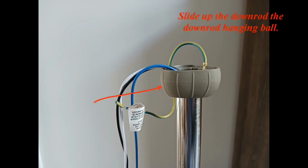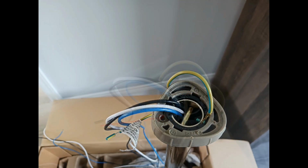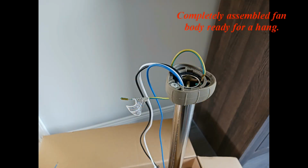Slide up the downrod hanging ball. Match notches on the hanging ball with the metal pin. Secure downrod's hanging ball with the screw. Completely assembled fan body ready for a hang.